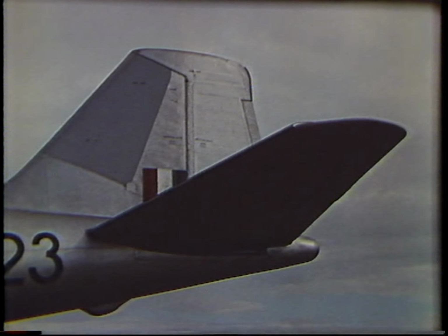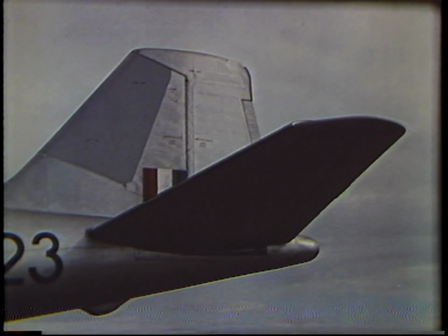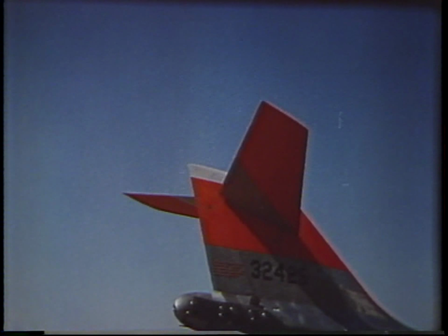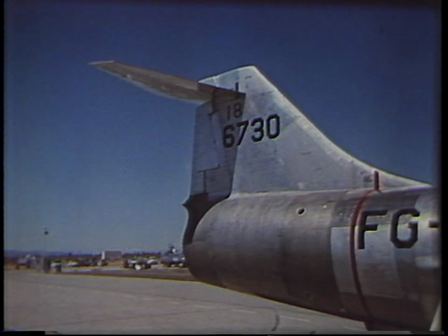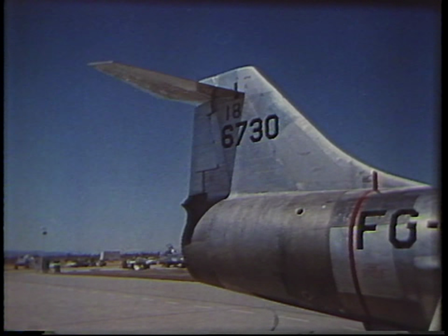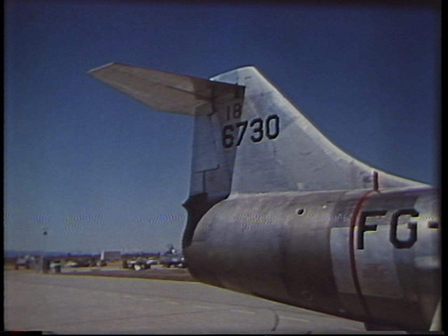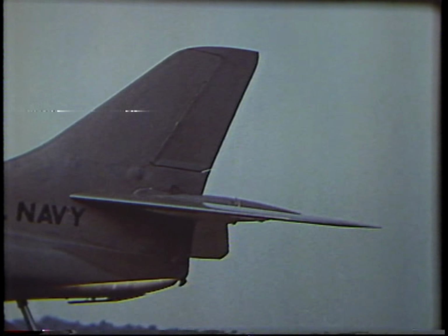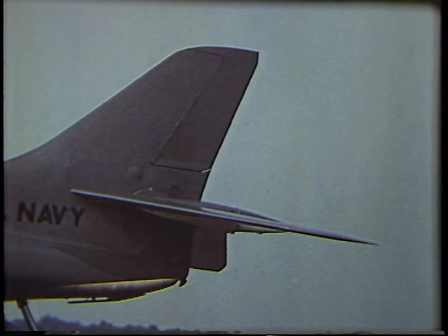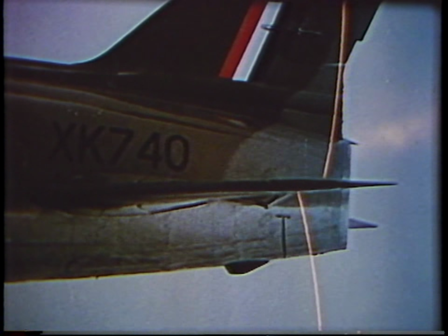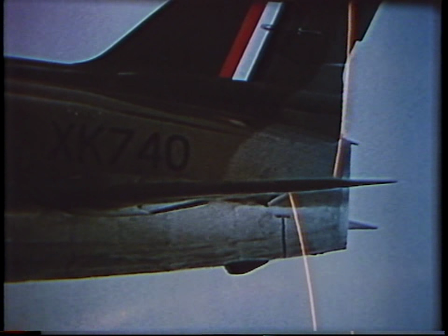Either the trimming tailplane with separate elevators, the all-moving tailplane with geared elevators, or a single moving surface called a slab tail. Such moving tailplanes can give up and down trim control with much smaller deflection than the elevators on fixed tailplanes.